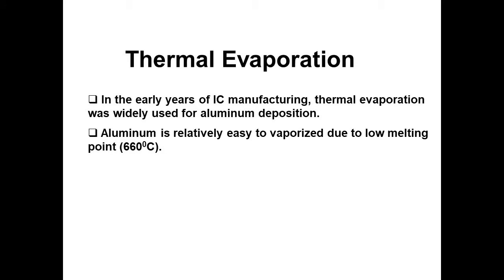For this section, we will learn about the metal deposition of the samples. There are a few methods to deposit the metals: thermal evaporation, electron beam evaporation, and also sputtering. In slide 65, we will be exposed to thermal evaporation. Thermal evaporation is usually used to deposit aluminium. Among the metals used in microfabrication, the one that is easiest to deposit is aluminium.